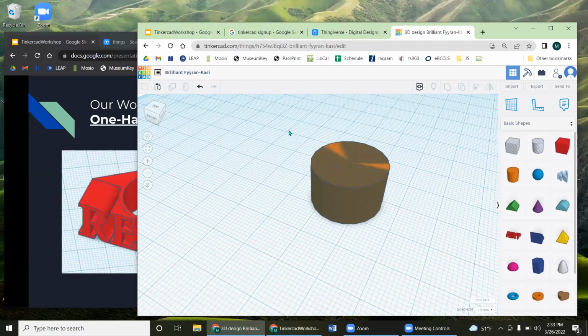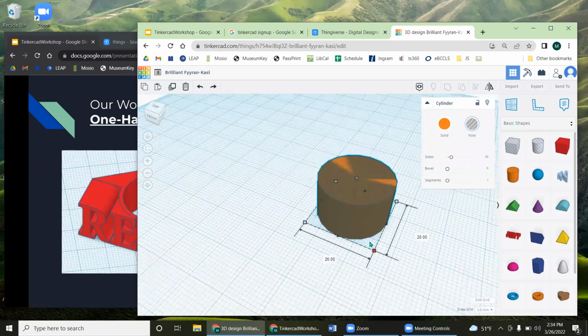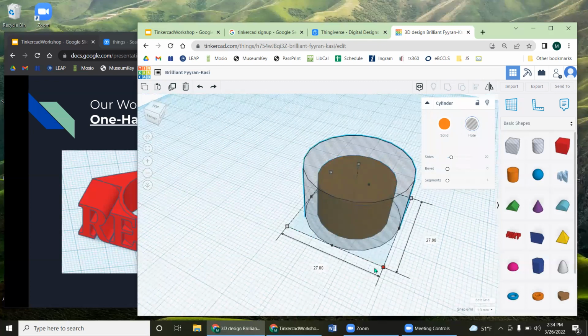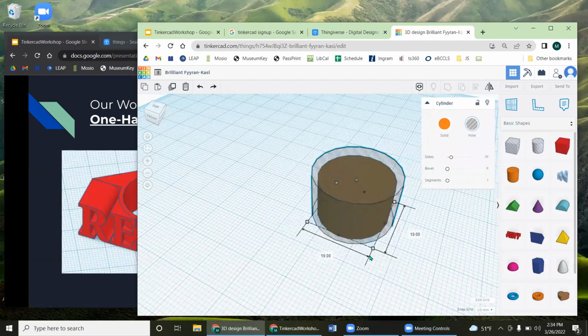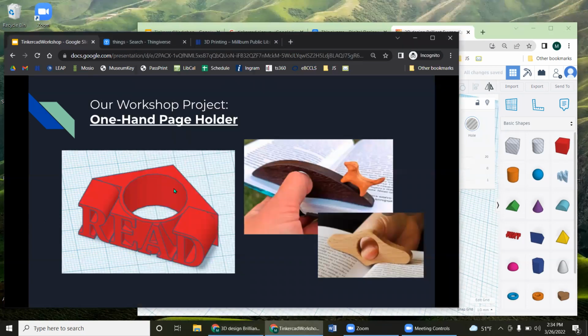It's difficult to choose that inside shape by itself, but if we just click and check that we have that, we can then hold Shift and hold Alt, because now it becomes useful to resize things from the middle. So now I can see it's scaling to the middle of the second object. That's going to help it get lined up and have a nice even ring. So I'm going to scale it all to the middle of that outside shape.